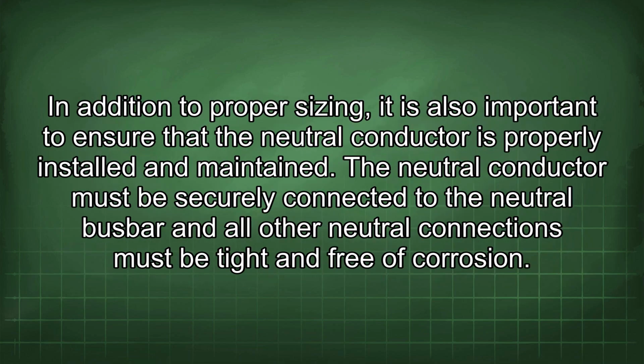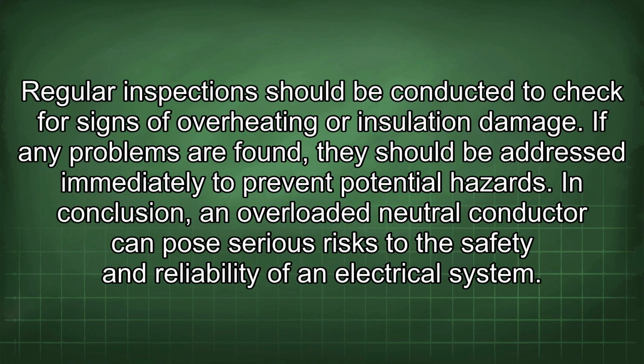In addition to proper sizing, it is also important to ensure that the neutral conductor is properly installed and maintained. The neutral conductor must be securely connected to the neutral busbar, and all other neutral connections must be tight and free of corrosion. Regular inspections should be conducted to check for signs of overheating or insulation damage. If any problems are found, they should be addressed immediately to prevent potential hazards.